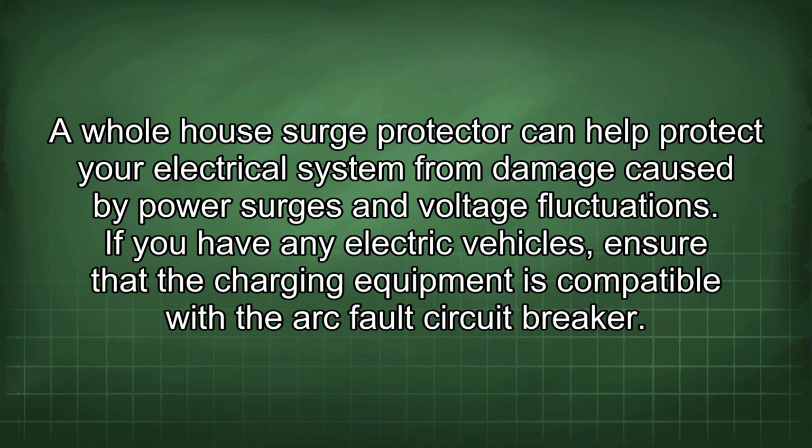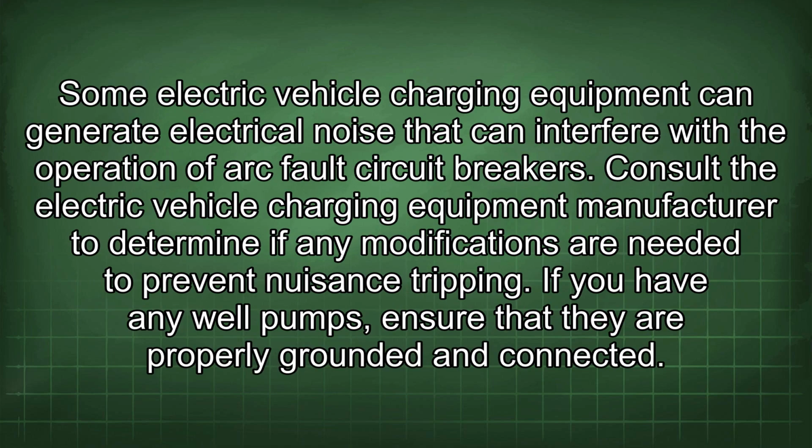If you have any electric vehicles, ensure that the charging equipment is compatible with the arc fault circuit breaker. Some electric vehicle charging equipment can generate electrical noise that can interfere with the operation of arc fault circuit breakers. Consult the electric vehicle charging equipment manufacturer to determine if any modifications are needed to prevent nuisance tripping.